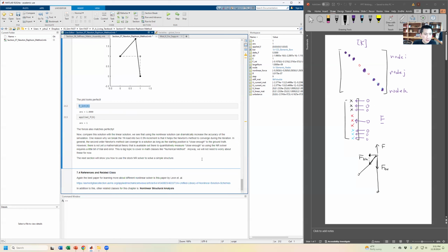So finally, related to the references and related classes, in civil or mechanical engineering, there are typically nonlinear structure analysis methods. Newton-Raphson is typically one of those second-order methods they will cover in the implicit method section. And then in the explicit methods, we typically would talk about Runge-Kutta, which is a family of nonlinear solvers that people can use to solve for the deformation of the systems without doing that in iterative steps to minimize the error. So those will be covered in that class.